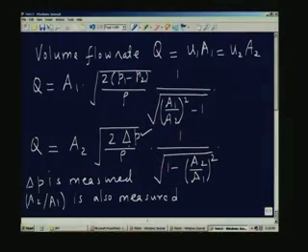Okay. So, I am going to basically use the measured pressure difference delta p and the value of a2 by a1, which characterizes the variable area device, and use this equation, which I will call equation number 4, as the basis for the measurement of the volumetric flow rate, assuming of course that the fluid is incompressible, or if the fluid is a gas, for example, the velocity is small compared to the speed of sound, such that the incompressibility assumption is valid. We have already seen this earlier in the case of the pitot tube.